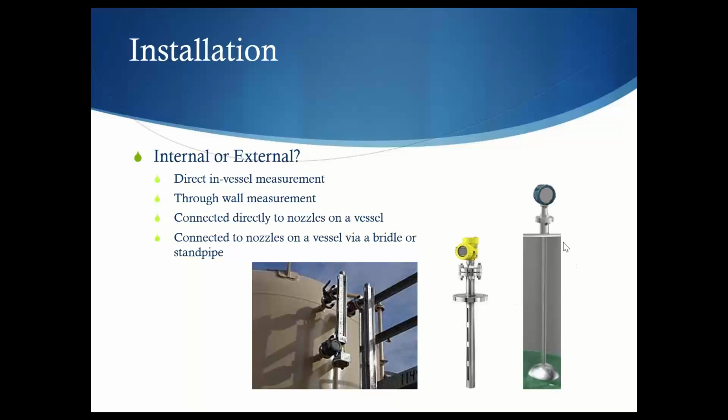The other thing you can have within the tank is a standpipe, and that's just to prevent things like foam and movements within the vessel causing the level to give you the wrong measurement.